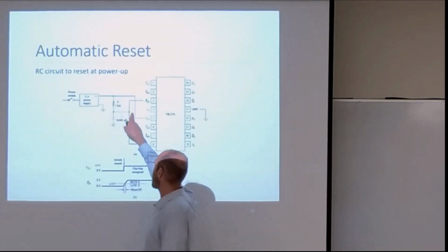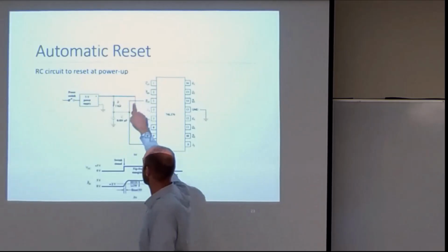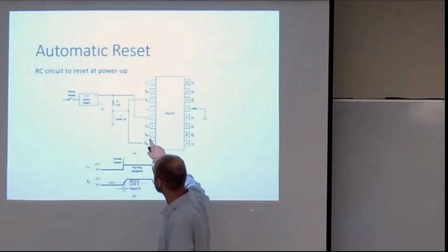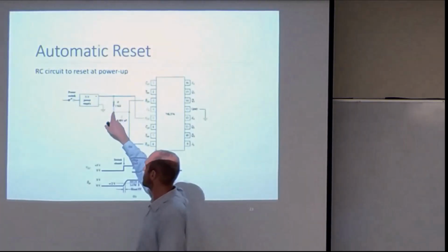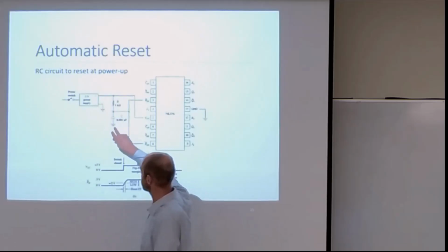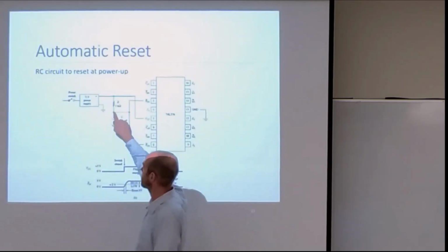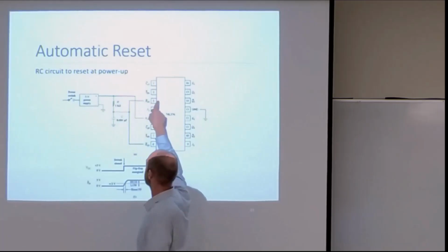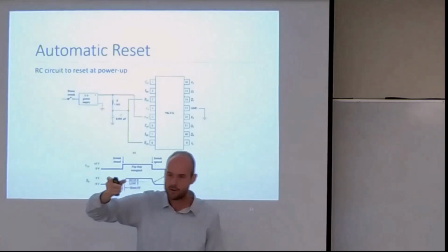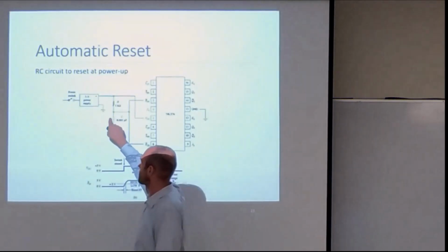So we are giving an active high to our power supply, but also to R1 and R2, which are a reset for a chip. Because they're active low, and all the current is being dropped over this resistor because this capacitor is not charged. This is essentially ground when you first flip on your power supply. So both resets are activated. Then as that capacitor charges, the resets will no longer be grounded as this charges up to your power supply.